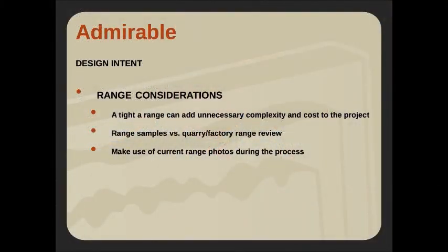One thing to think about as well, depending on the nature of your project, the size, the scope, the scale: do we want to specify a range sample at the quarry or the factory, as opposed to just using range samples to approve our material? The typical submittal process, of course, we all understand: we're going to have to submit samples, and everybody's going to look at it, approve it, reject it, whatever that process becomes. But sometimes it's more conducive to go to the factory or to the quarry to actually view slabs, to view a mock-up, or whatever the case may be.